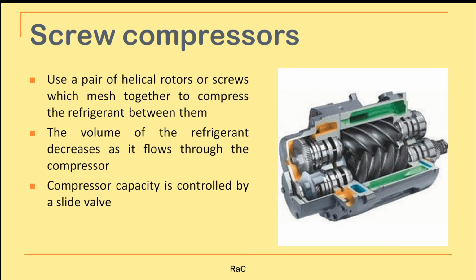Now coming to the screw compressors, a pair of helical screws or rotors which are meshing together as shown here. So they compress the refrigerant between them. So the refrigerant will be admitted, and when the screws are rotating in the opposite directions, it will get compressed and will be discharged. Same thing, the chamber volume gets reduced, as a result of that pressure will be increased.